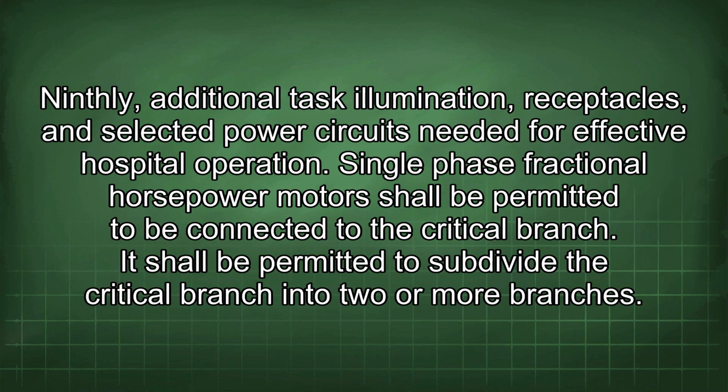Ninthly, additional task illumination, receptacles, and selected power circuits needed for effective hospital operation. Single-phase fractional horsepower motors shall be permitted to be connected to the critical branch. It shall be permitted to subdivide the critical branch into two or more branches.